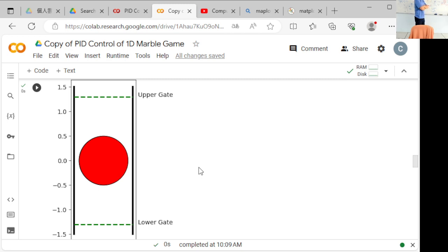In order to avoid overshooting here, we would need to know the velocity, right? Now, unless I have a vision system, I won't be able to estimate the velocity just like that. But what we can do is use the time at which we trigger the lower gate and the time at which the lower gate is cleared again.